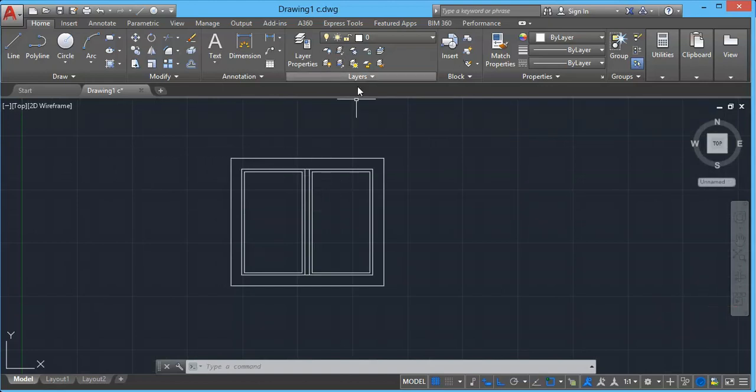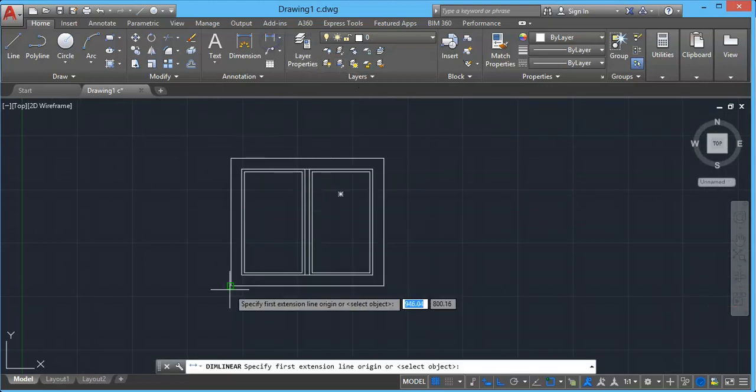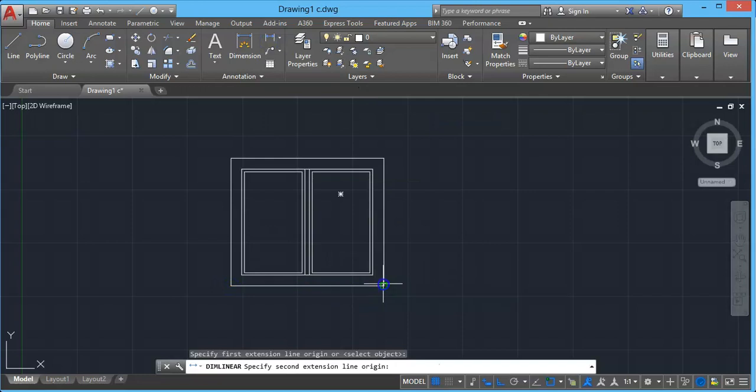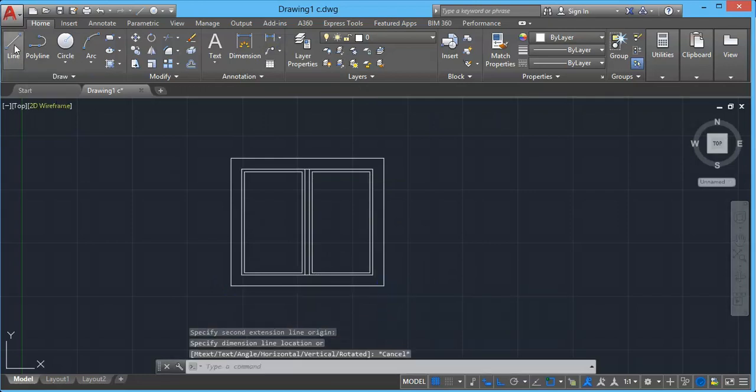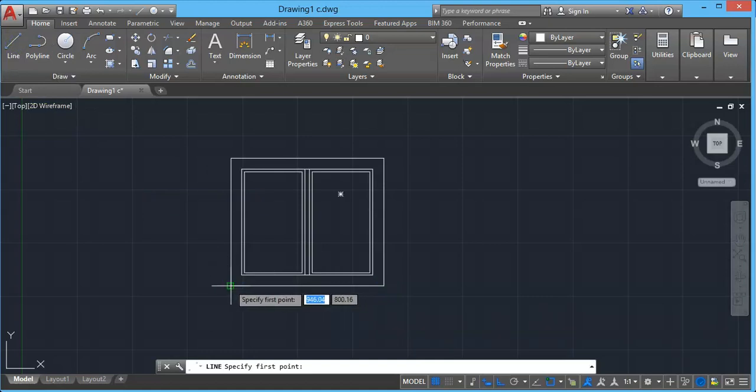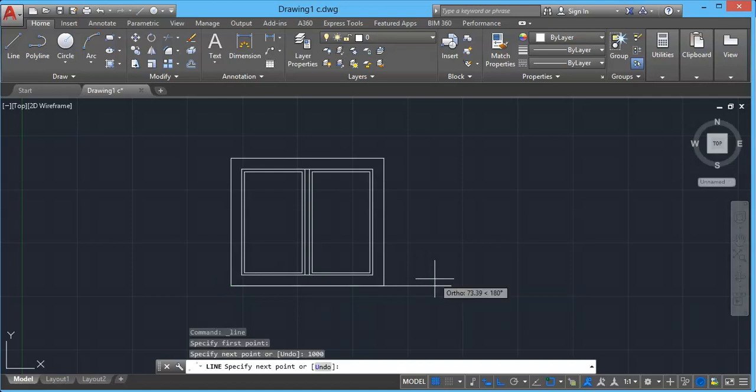Before that, let's measure the object. It is 700 mm. What if I want this geometry to be 1000 units? Suppose I choose a line, click here at the edge, type 1000 units and escape. So I want my geometry to be 1000 units till here, this line.